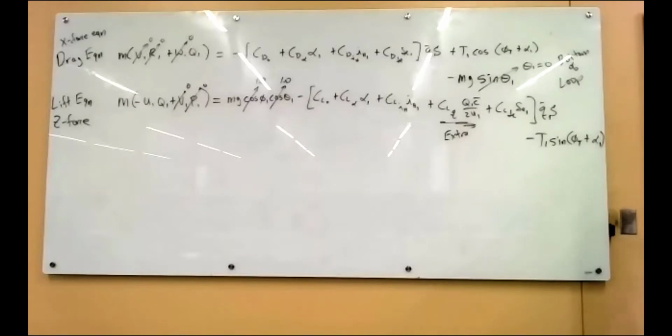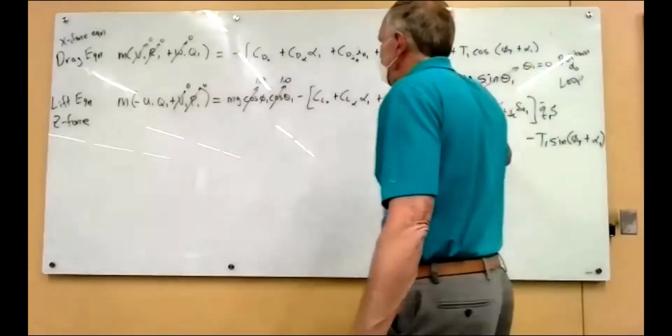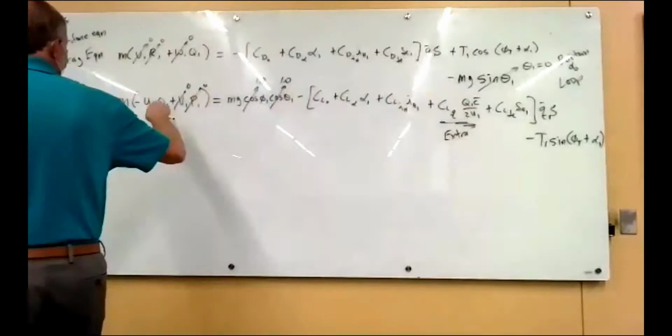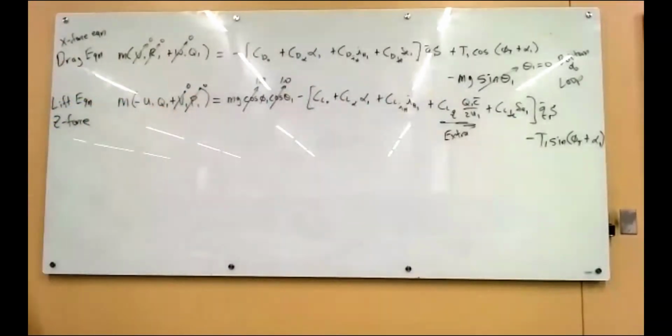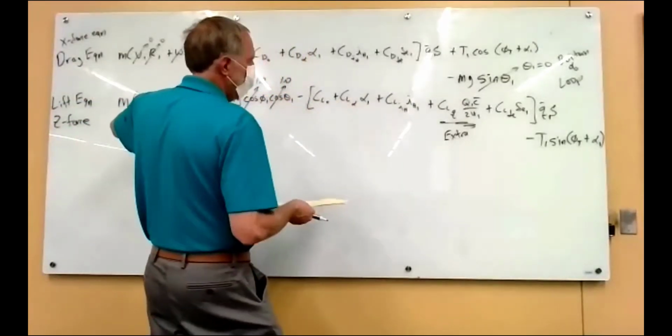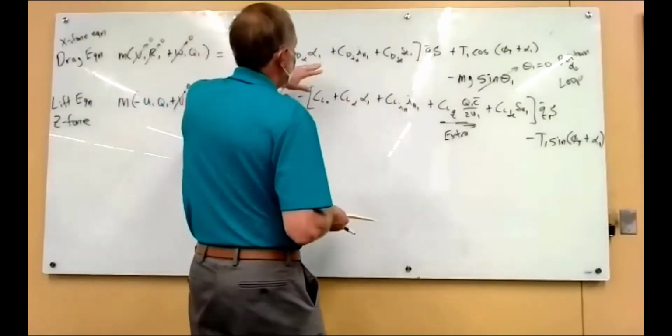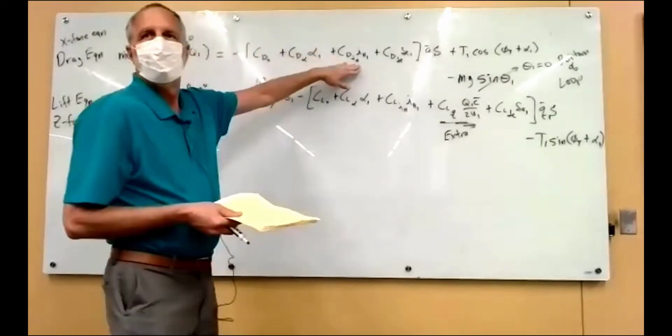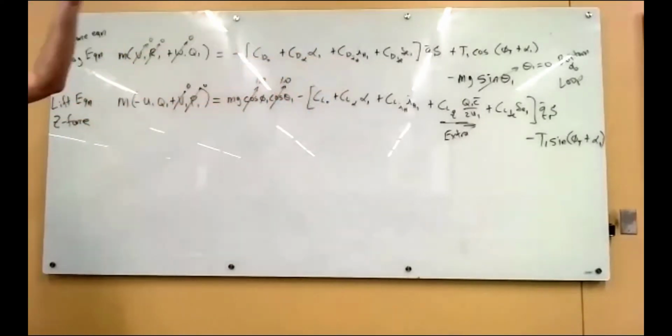So these equations should look familiar because we used these exact equations for the cruise flight condition. The only thing different is that Q is 0 in addition to P and R, so those terms all got knocked out. And fundamentally, it becomes lift equals weight in the cruise condition and thrust equals drag. But we're doing a pull-up, a maneuvering flight, so those Q terms show up in there now.